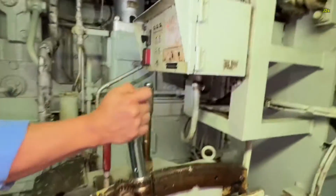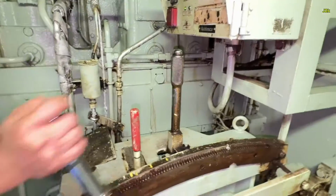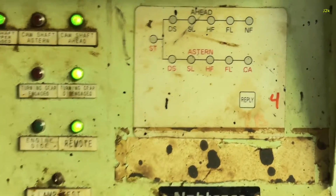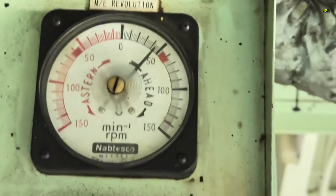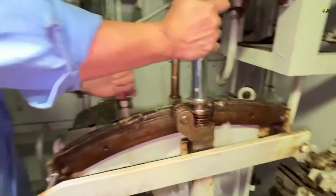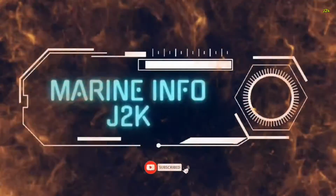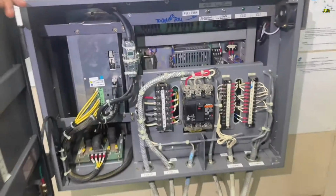Check the dead slow astern. Stop the engine. Start the engine to dead slow ahead. Dead slow ahead. Check the RPM condition. And now we have to continue our underway by maneuvering at engine side condition. On arrival in port, we have to carry out the electrical troubleshooting.